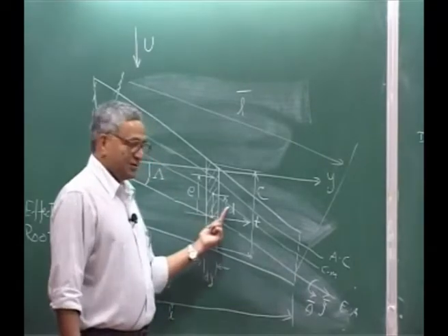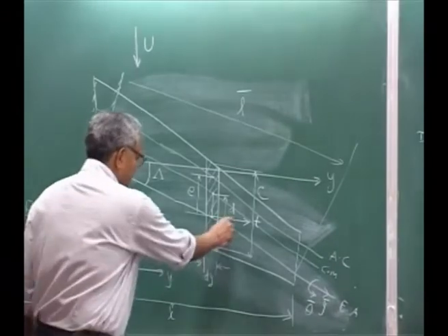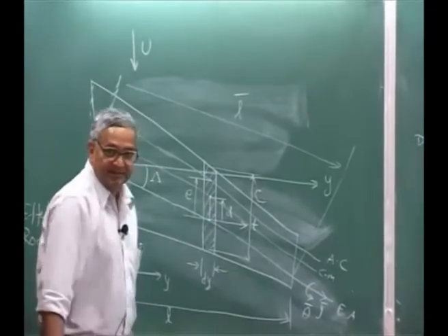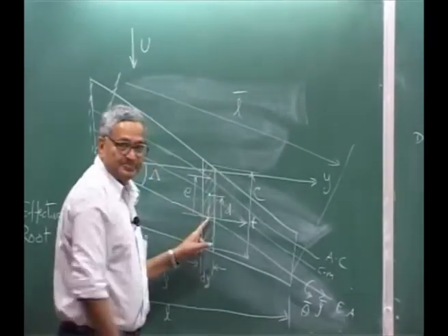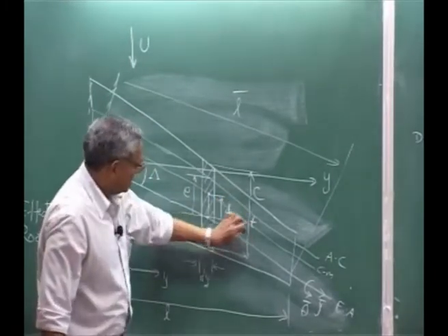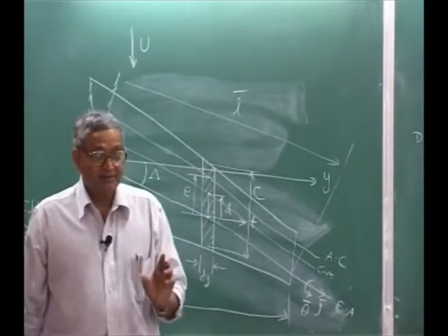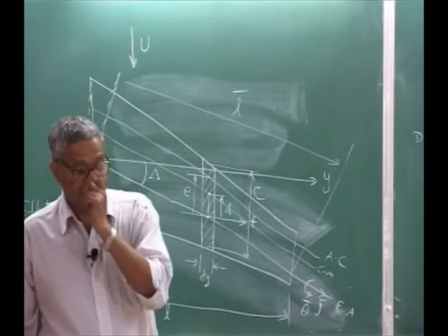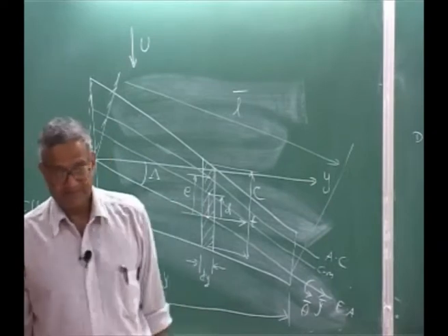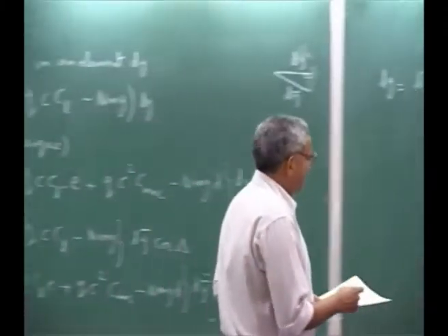What will happen is the perpendicular component is like a bending moment, because if I resolve T, one along the y bar axis, another one along this is a twisting moment. This will twist and that will also twist. The twisting will become like a distributed twisting moment in the bending direction. And that's what we have to now resolve.